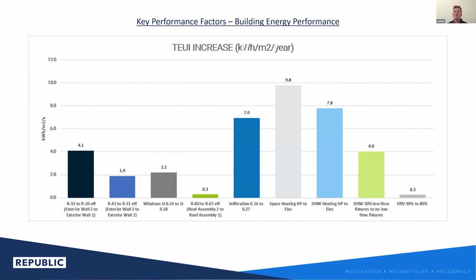This leads us to a series of both material and detailed design choices to really ensure that this is executable and we're able to achieve the air infiltration rates that we're using in our models on site. Based on the performance we're seeing from what's been tested on site to date, we're quite conservative in our estimates in terms of an ACH target of 1.5 ACH at 50 Pascal.